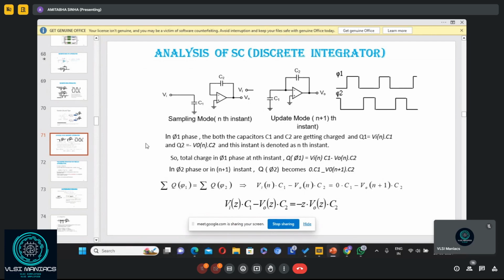For an example, you have a typical passive LCR circuit. How is the equation of the LCR circuit governed? If the excitation voltage is v(t), then v(t) equals i(t) times R, plus L di/dt, plus 1 by C integration of i dt. Once we get this equation, we know that R means resistor. We'll use a resistor. It's a series circuit because three things are added.